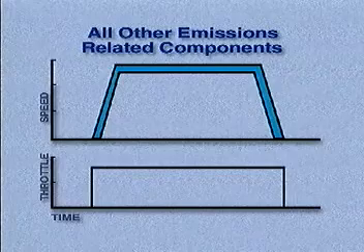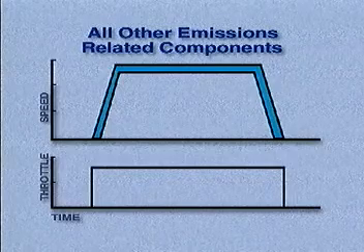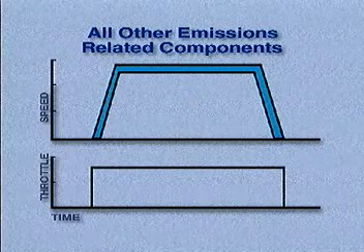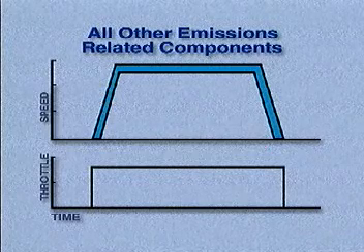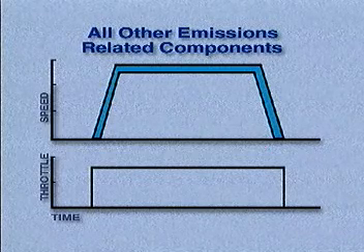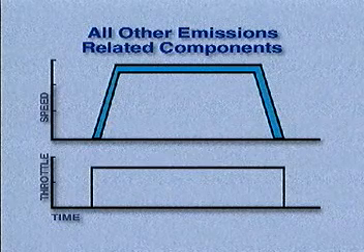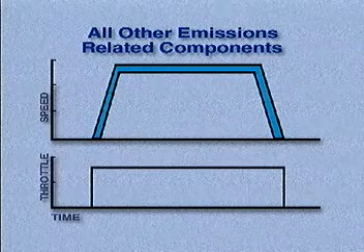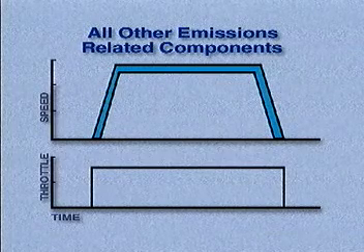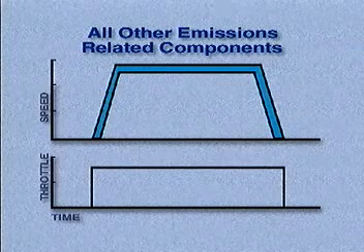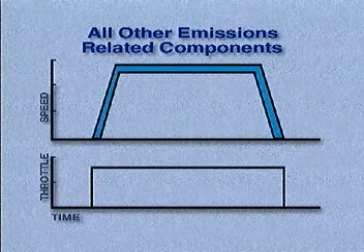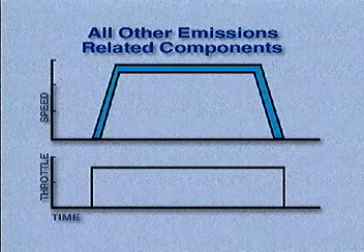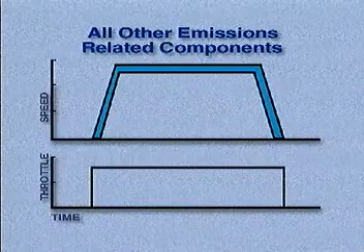Allow the engine to idle for 5 minutes or more with the lights, coolant fan, and all accessories, including the air conditioning, off. Verify the completion of the readiness tests. In general, if a readiness test is completed and no DTCs are present, and the malfunction indicator lamp does not light, the repair has been successfully completed. If any DTCs are still present, follow the diagnosis and repair procedures in the service manual.